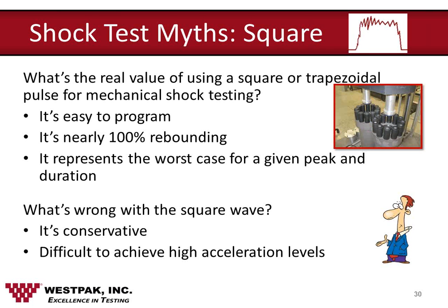So they're easy to program. On the negative side, this trapezoidal pulse is conservative in that it's rarely seen in the real world environment. It's also difficult to achieve very high acceleration levels because you simply can't get enough nitrogen gas into the cylinders.